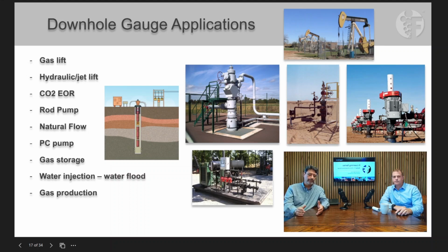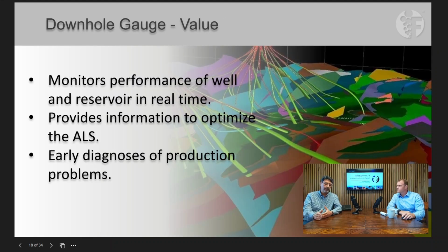For instance, some customers in the past basically used that downhole vibration information to learn, over different cases that they discovered over time, what vibration was tied to a particular issue. For instance, when there was a lot of gas going through the pump, the vibration is different. When the elastomer of the pump is breaking in pieces, there is a different level of vibration there.